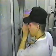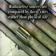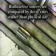ALARA dictates that engineering controls must take precedence over administrative controls whenever practical, and several engineering controls have already been incorporated into the design of nuclear gauges. One simple engineering control is to use the smallest source practical. By small, we don't mean physically tiny. Radioactive sources are compared by their decay rates rather than their physical size. Decay rates are measured in units of disintegrations per second.